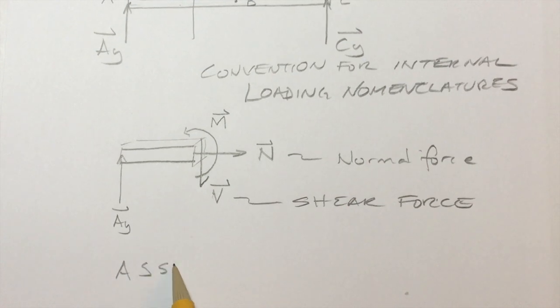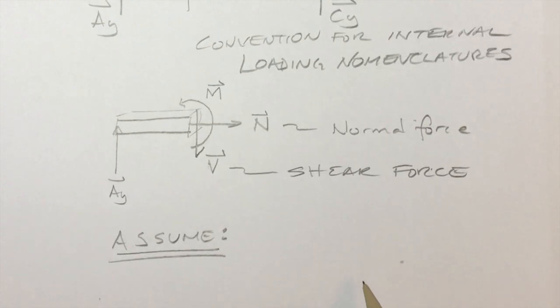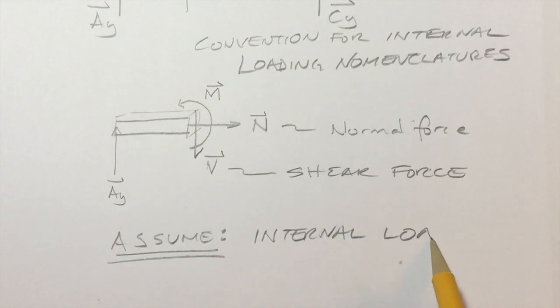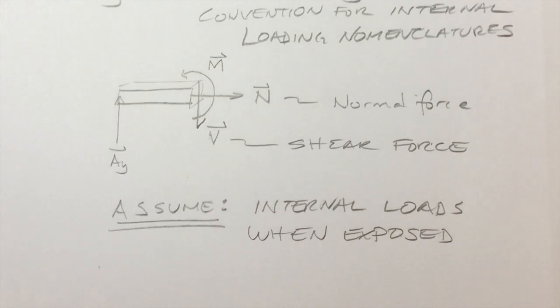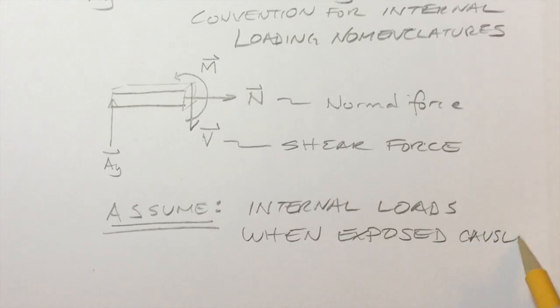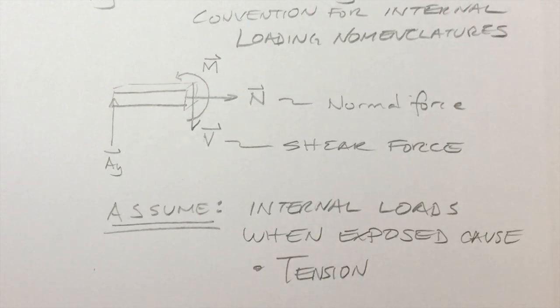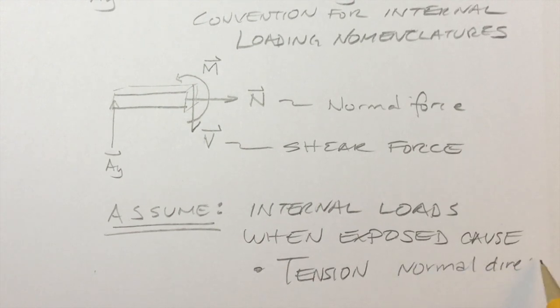As you can see, I've assumed a specific direction for these internal loadings. So let's be consistent as a class. We'll always assume that the directions of those loads are as follows. Okay, so assume internal loads when exposed cause tension. So that'll dictate the direction of your normal force.